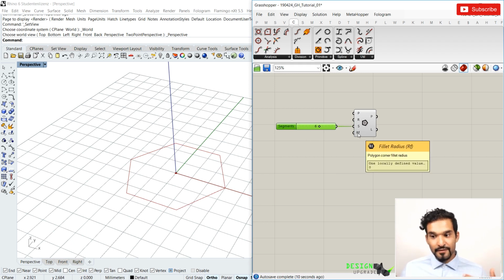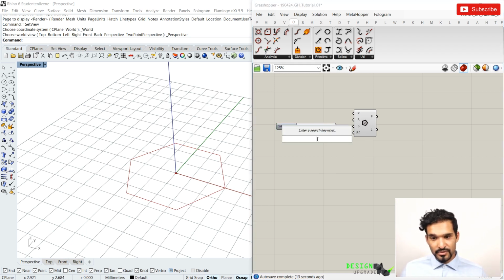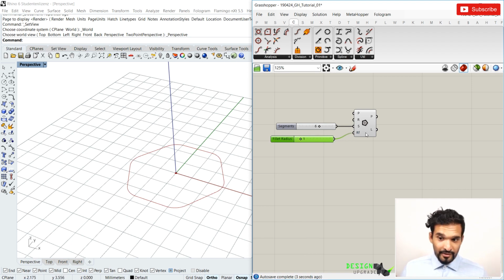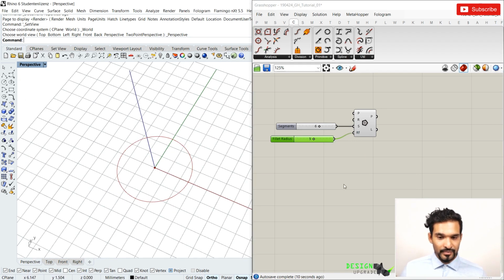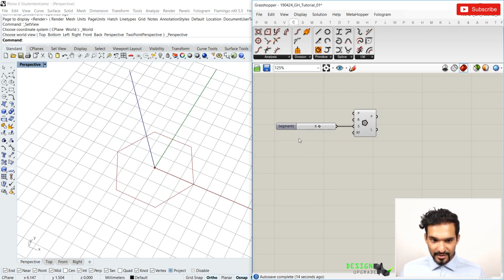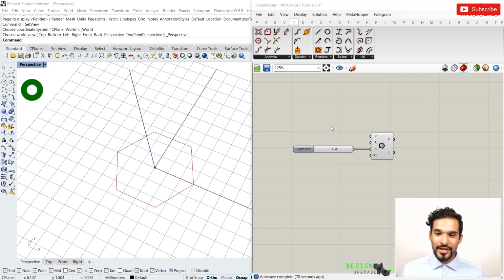And this here is actually a fillet radius mechanism, so you can just, for instance, hook up something like so, and this will fillet your geometry on the corners, always calculating a radius. Now, if you have a higher radius, in this case, this will result in a circle-like shape, okay? But we will do a fillet afterwards, so currently we can just delete this, okay? Perfect.